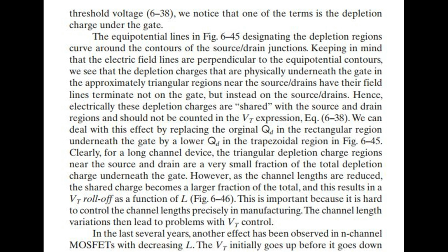Hence, electrically these depletion charges are shared with the source and drain regions and should not be counted in the threshold voltage expression, Eq. 6.38. We can deal with this effect by replacing the original Q_D in the rectangular region underneath the gate by a lower Q_D in the trapezoidal region in Fig. 6.45. Clearly, for a long channel device, the triangular depletion charge regions near the source and drain are a very small fraction of the total depletion charge underneath the gate.